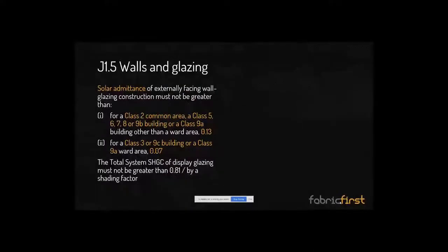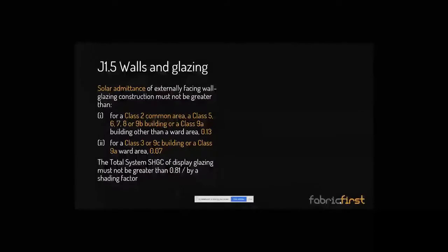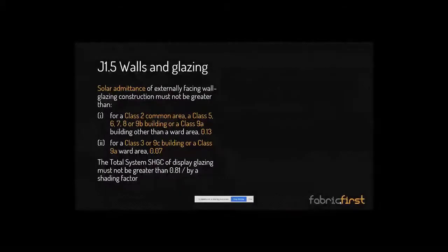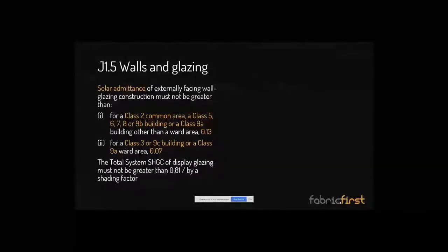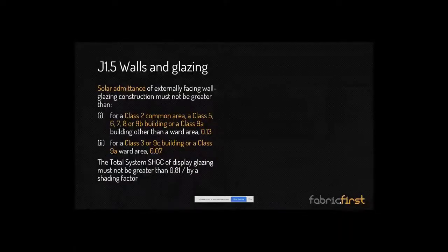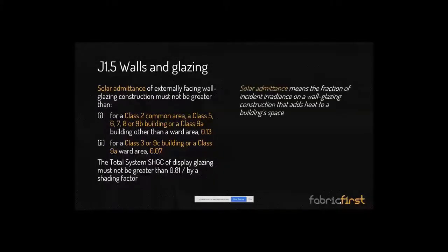If you walk through Melbourne and you look at dark buildings, you'll see that a lot of them were built before 2010, because that was the design response at the time. We're going to be going back that direction unless you start offsetting the areas of your glazing to account for it. So bring down your window to wall ratio, make it generate smaller values for the window to wall ratio. You'll get a flexibility from an aesthetics point of view. Again, there is a bit of a backstop for the display glazing. I won't go into that definition.